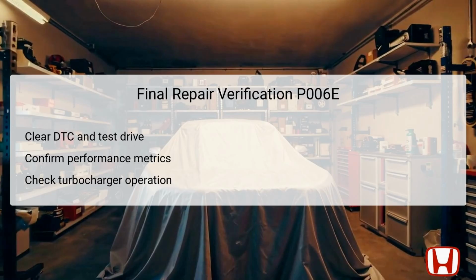Monitoring performance metrics is crucial. Ensure that the vehicle accelerates smoothly and that no warning lights activate. Make sure to check the turbocharger operation, which includes reviewing the wastegate's response to engine load. A steady operational performance post-repair validates that the troubleshooting and repair process was successful.